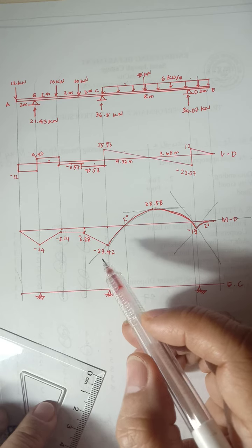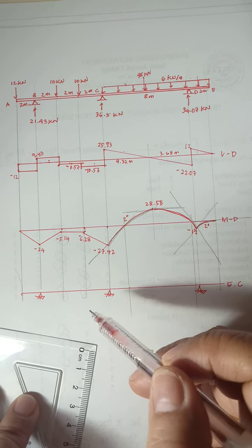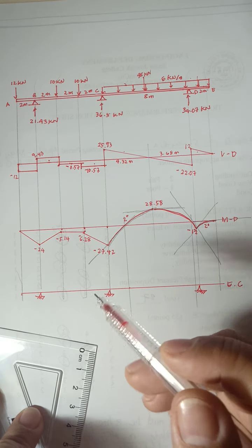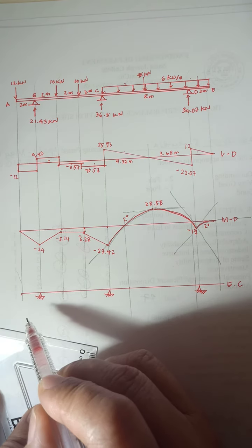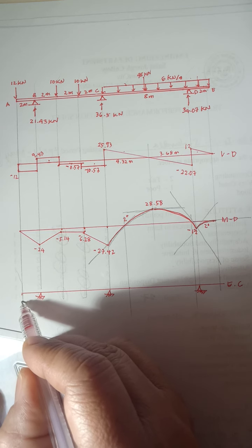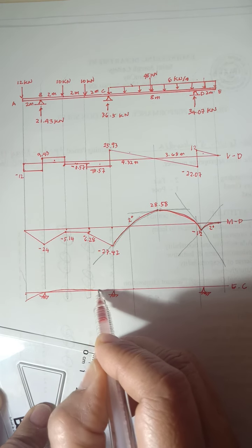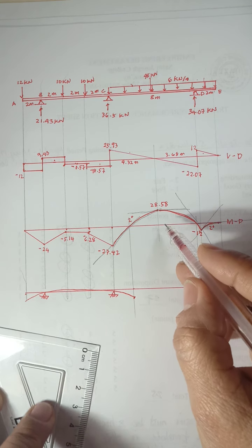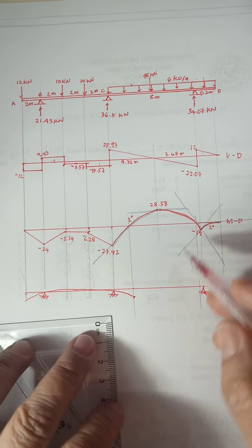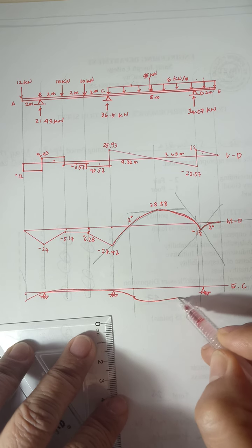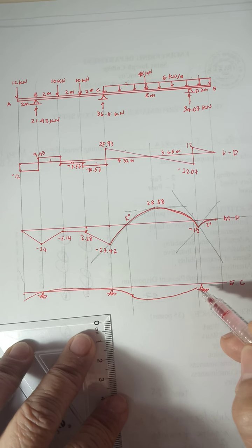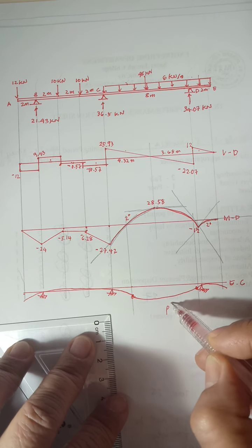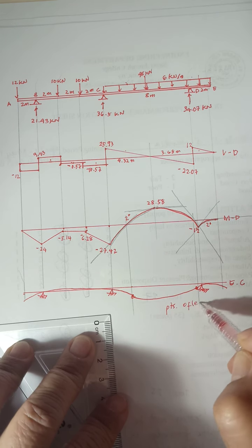So we said that if it is negative moment, the curve is frown, concave down. Okay, and then this is positive moment, so concave up or smile. And the negative moment, so concave down. So these are your points of inflection.